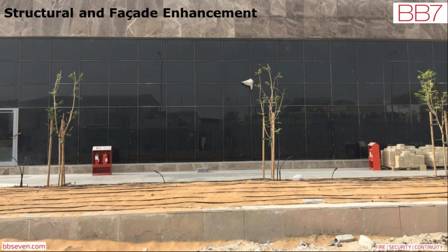Now, architecturally, there's minimal change to the outside of the building, and internally, there's little impact on cost and spatial layouts, demonstrating that architectural visions can be retained while still achieving very high levels of security and for much less expenditure than people envisage. The standard engineering approach would be to reduce the degree of fenestration or make the glazing panels smaller, and then using expensive blast-resistant glazing and framing to engineer out the solution. However, this solution used a structural solution behind a standard facade, using innovation rather than certified products.